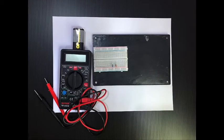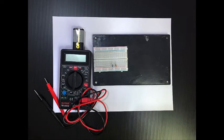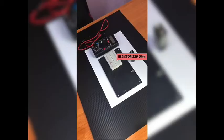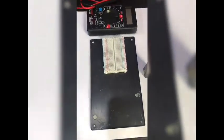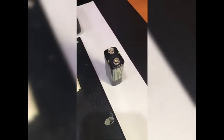Assalamualaikum and hi everyone. My name is Adi Babantu Johari. So today I will show you how to measure resistor and DC voltage. First of all, I will introduce you to the equipment that will be used in this activity. We have a digital multimeter. Second, we will use a 9 volt battery and a breadboard, and lastly we will use a 220 ohm resistor. In this video we have the resistor, breadboard, 9 volt battery